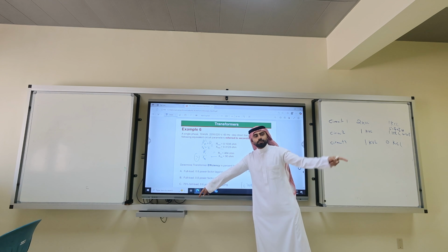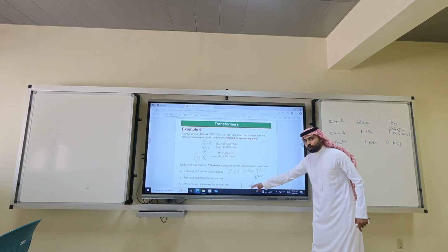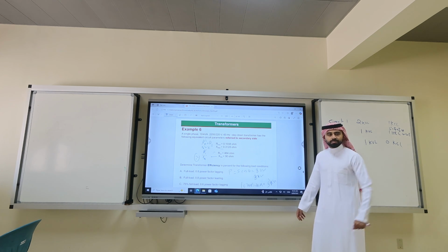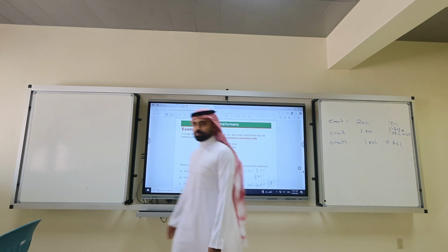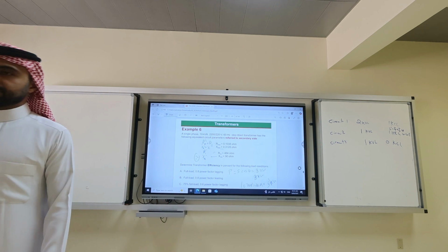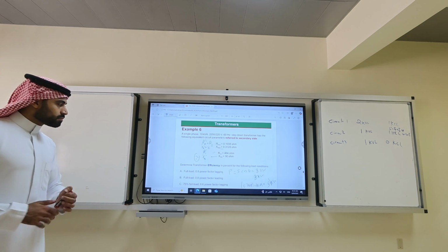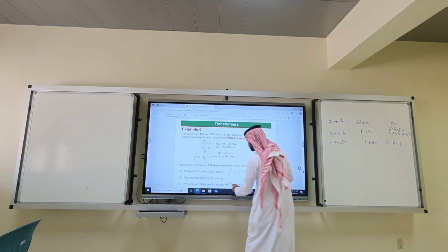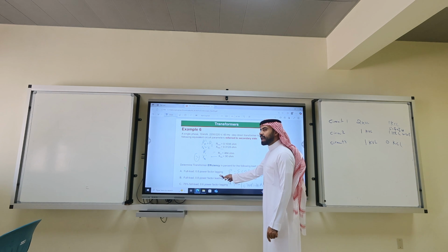It means 7.5 times 0.6, or 10 times 0.75 times 0.6 kilowatt. Calculators, what is this number? The same as above, right? 10 times 0.8 for A and B. Yes. What is part C? Calculators? 4.5 kilowatt. Lagging and leading have nothing to do with the real power, they have to do with theta.